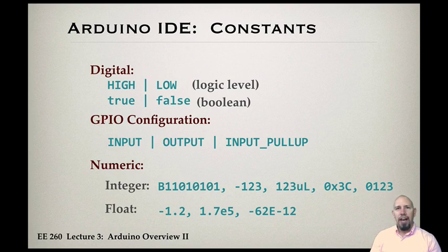And in terms of defining constants that you want to use, there are a number of formats that can be used. So you can have integer formats. For example, I can define something as a binary. If I define a number to be binary, then I get 8 bits, and so I can define all those bits. So binary is one way of defining a constant. I can define it as an integer. Notice here I have a negative sign; an integer can be positive or negative.